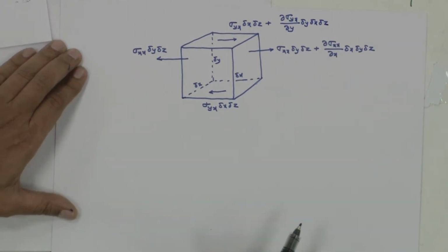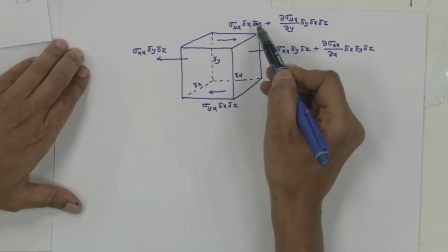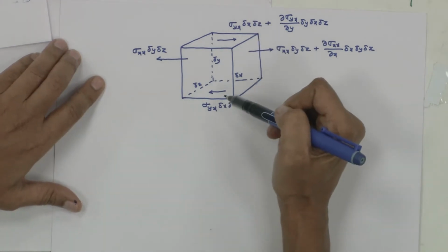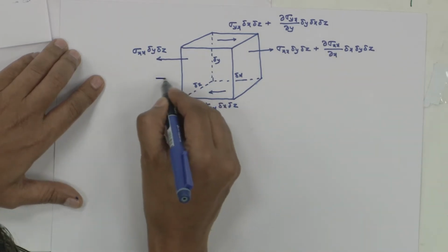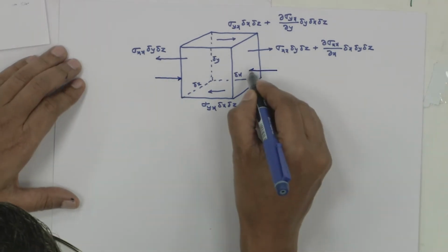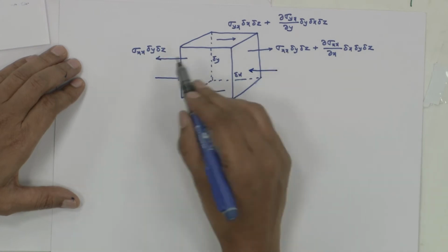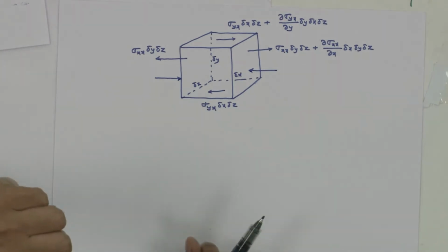Now which forces have we completed? Normal stresses and shear stresses. What is left out in the surface forces is pressure. Now you see, pressure I am taking left to right. Pressure always acts inwards and normal stresses always act outwards. This is one question students are going to ask, why is pressure taken inwards? Normal stresses taken outwards is natural, we all understand, because we would like to take it as stretching, so that's why we take it outward. But why is pressure inwards?